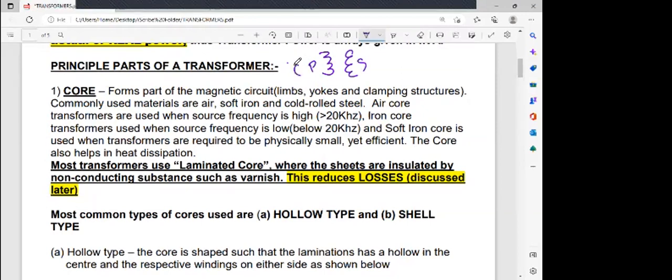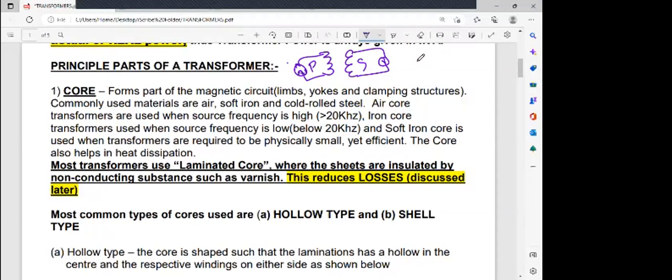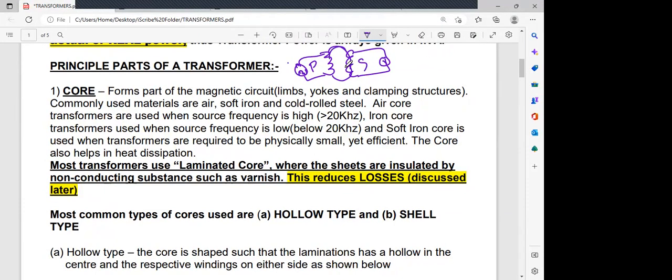And as long as we are going to give an AC source to this, you will have electromagnetic changing lines of force over here that is going to cut your secondary and you will get a voltage output over here. You'll get a voltage out. The lines of force are cutting this secondary, but not all the lines of force.